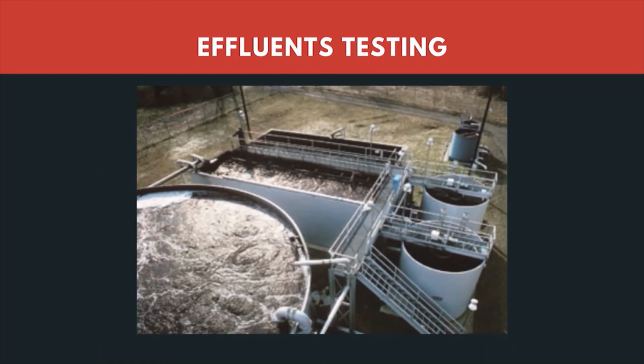And finally, the refinery is also generating a lot of effluent. In the previous episodes, I was mentioning the effluent treatment. The effluent, before being let out into an aquatic body, needs to be tested, and the results need to be shared with the pollution control authorities. You cannot afford to let out the effluent as it is without sampling it and analyzing the chemical constituents of the effluent. So, you have to thoroughly test it, and only then let it out into any of the aquatic bodies, and these details also need to be shared with the statutory authorities.